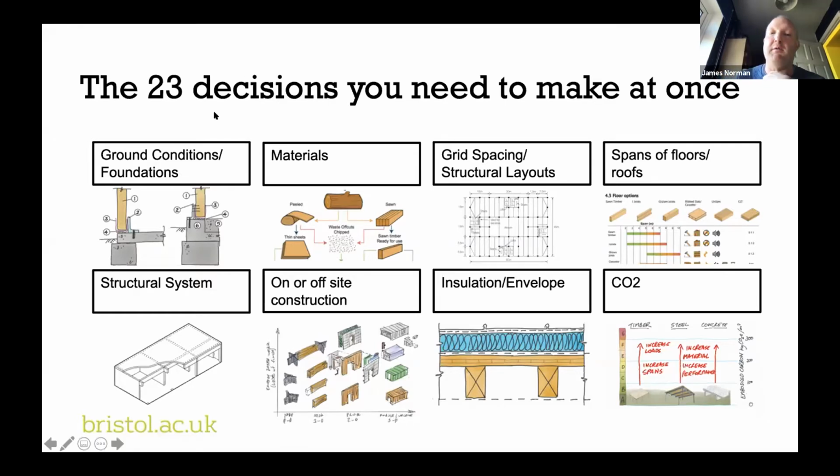So that decision might influence the material we use. At 7 meters, timber works, but it's really at the top end of what is available and what is ideal and suitable for timber. We're going to be governed by deflection, vibration. It's going to make the amount of timber in our building significantly greater. It may well impact the cost, therefore. Whereas that is an ideal span for a concrete frame building or a steel frame building. So just that simple decision has ruled out materials.